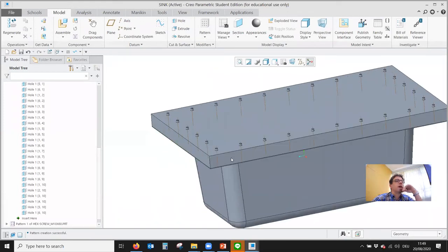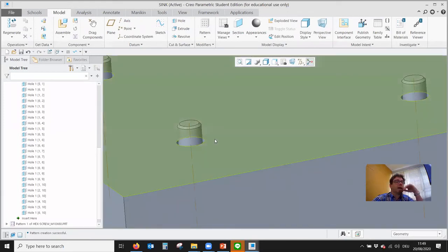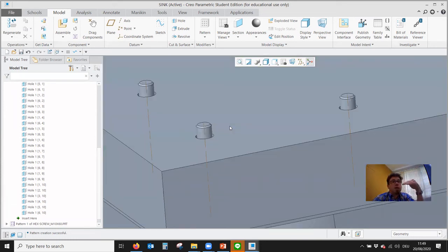Now the nut is still missing, and I said actually before you can place this group two ways. You could create a sub-assembly, a separate assembly, only with the nut and the screw in there. Of course, you would have to put in the exact distance that you need, and then you just pattern this assembly. You can do that. However, here it's better to actually put in the nut separately, and then you can maybe later make a design change, and the whole assembly will change accordingly.